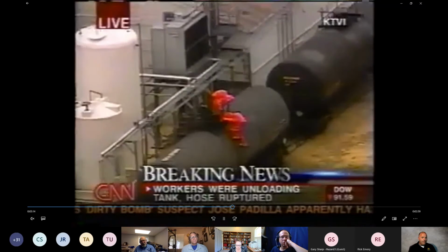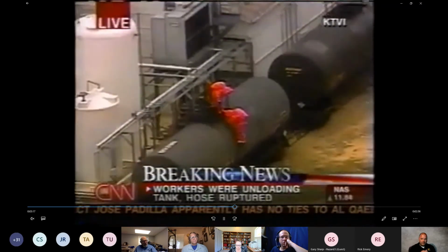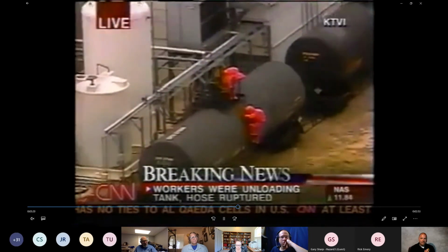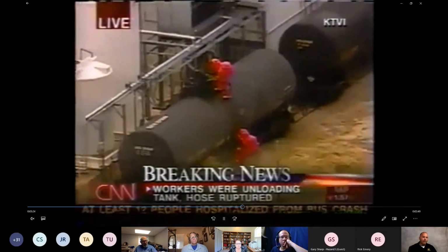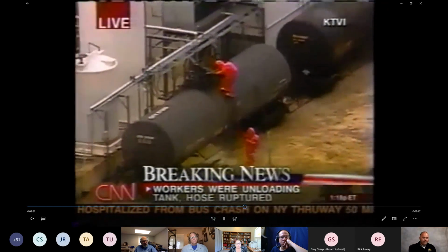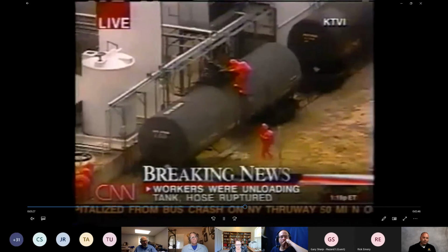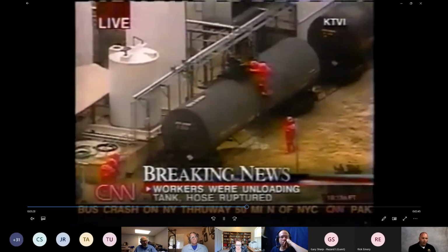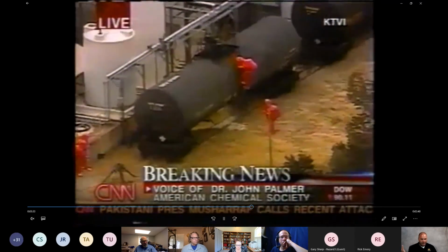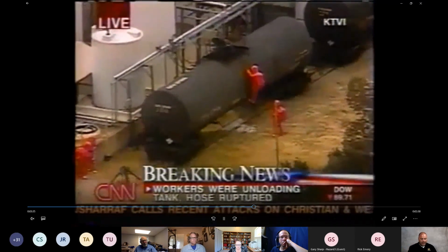If I had this leak, and this is just me speaking here, if I have a liquid leak, I would seriously consider opening up the vapor lines, because why is it pushing out of there? Because the vapor pressure on the top is so high, pushing it out that hole. If I release the vapor side, there's no push anymore, right? So that would clear up my whole problem.